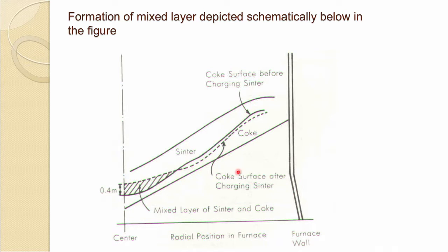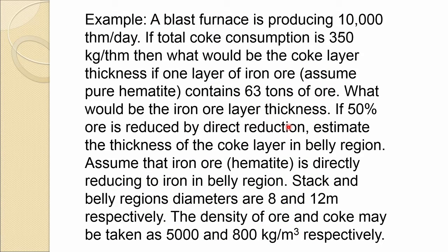So, these are a few situations which may arise in charging, and one should avoid them and take proper care of these things, because this will lead to maldistribution of the gas flow and eventually affect your reduction and heat transfer. Okay, so one example based on this is given here.